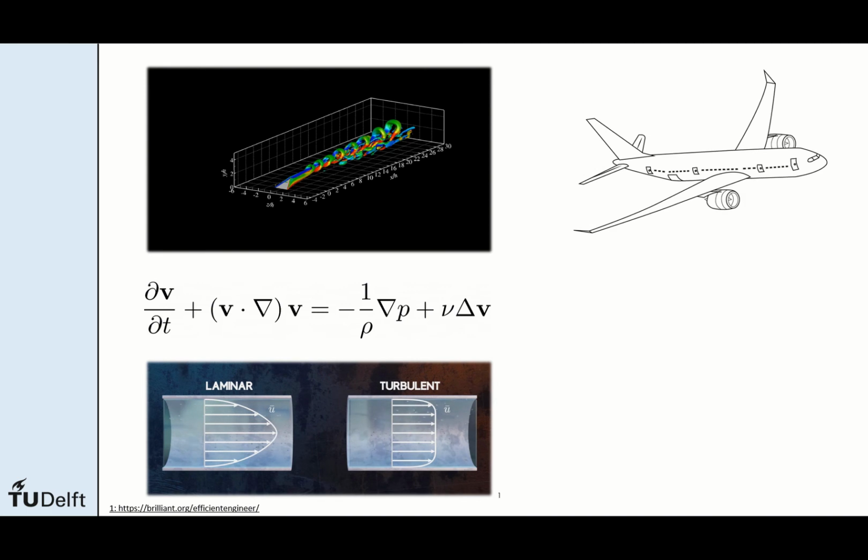In our research group, we study the process by which laminar airflow transitions towards a turbulent state on the wings of subsonic aircraft. Wings are not smooth, but rather contain surface imperfections. Misalignment between wing panels in the manufacturing process introduces roughness in the form of spanwise-distributed steps, which promote laminar-turbulent transition and render large areas of turbulent flow. As a consequence, the skin friction drag increases, which carries an important economical and environmental impact.